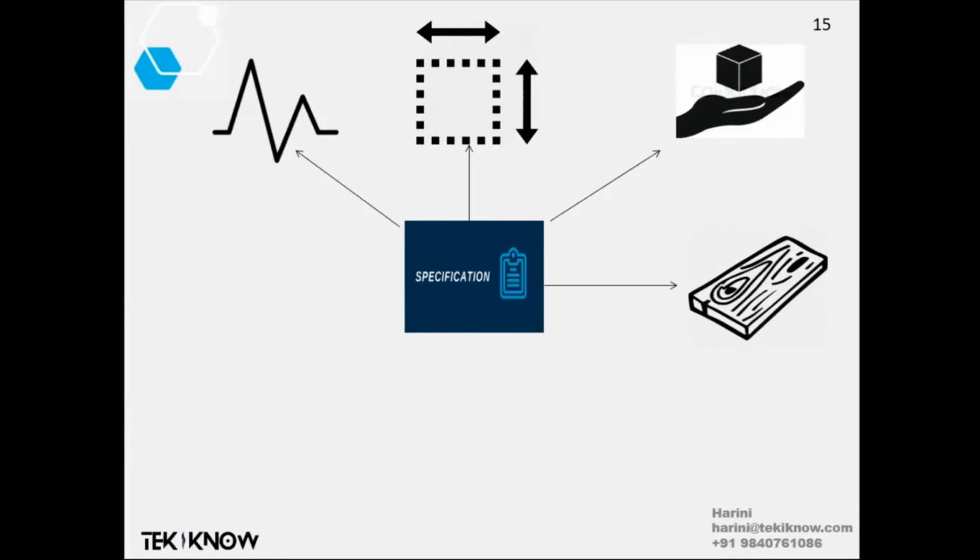You need to place the order abroad. But if you do your 5G antenna in FR4, that may melt and doesn't give a good result. That is like a dummy antenna, never used in a product.